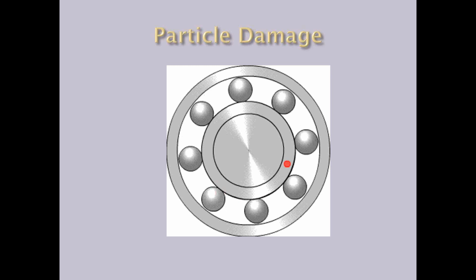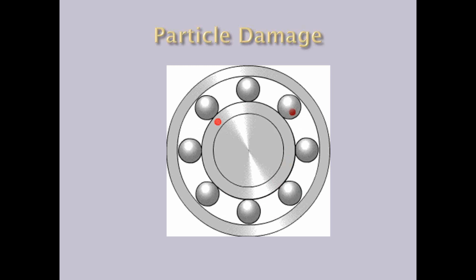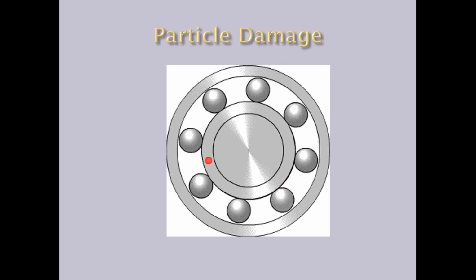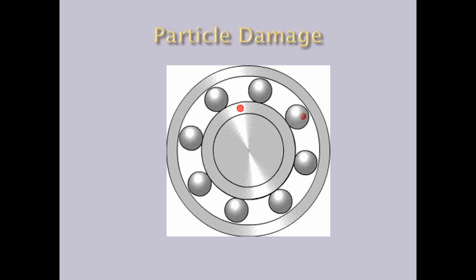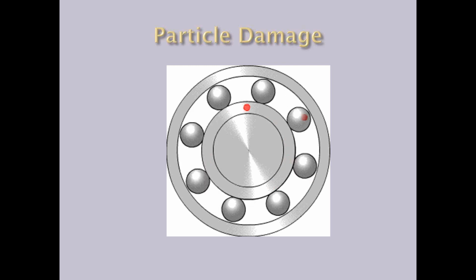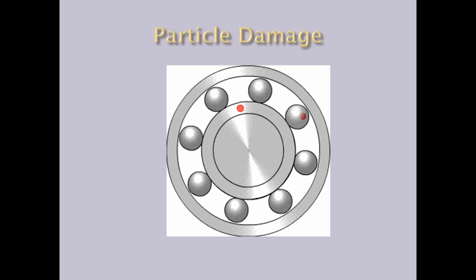And I'll ask questions about this rotating bearing here. How many bearings in your plant do you have that turn this slow? Probably not many. A lot of them are turning 900, 1800, 3600 RPMs. And then how many bearings in your facility only have 2 particles in them? Well, the answer is none. They have hundreds of thousands and millions of particles in there. They're turning 1800 revolutions a minute. Figure that out for a day, a week, or a year, how many times those particles come in contact with the loaded surface, and you'll see why your bearings wear out. But if we could eliminate all the particles in there, the bearings, in theory, could last.